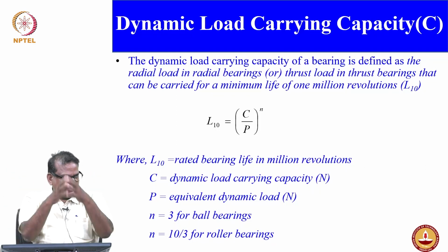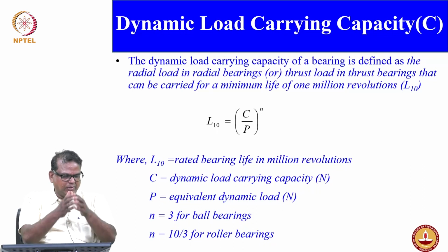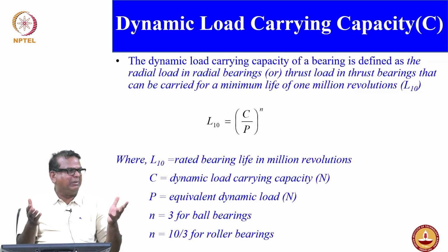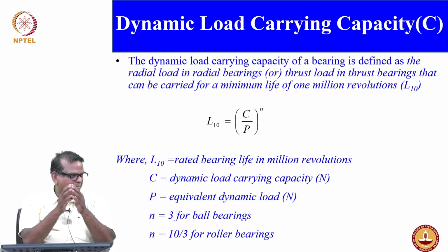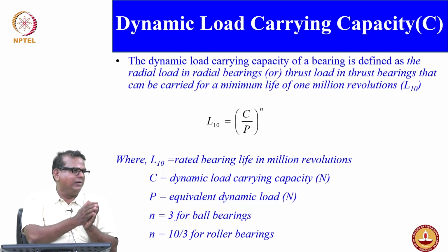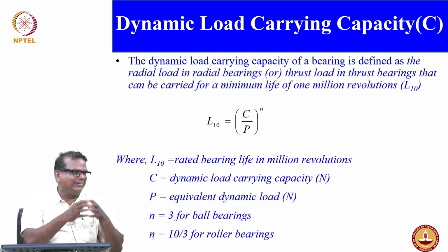In that, 90% of the bearings should not show any evidence of the pitting aspect. That means only 10% can fail. That is the reason it is called L10 life.